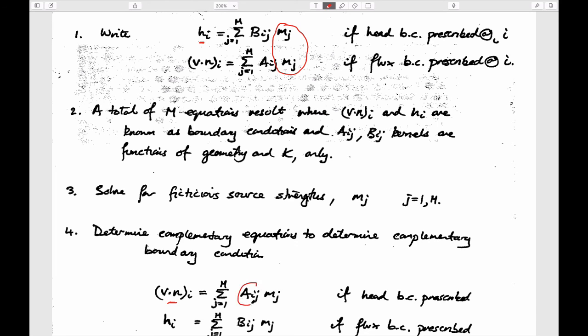We'll use the different magnitudes of these Green's functions, but they're linked together by the same values of the source strengths that we had from before. And so that's basically the solution. So we calculate what these source strengths are that satisfy the boundary conditions. So these are BCs. These are sources, which we don't know, the strengths. Once we know what these sources are, because we know all of the boundary conditions, and we know all of these functions here, we can calculate this.